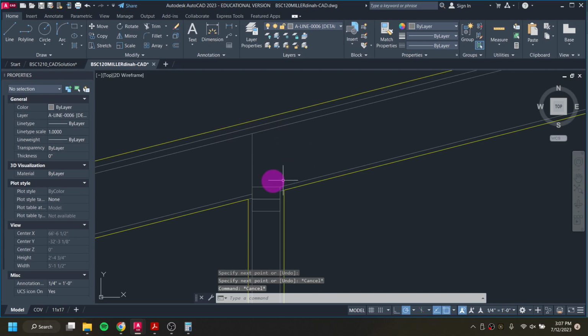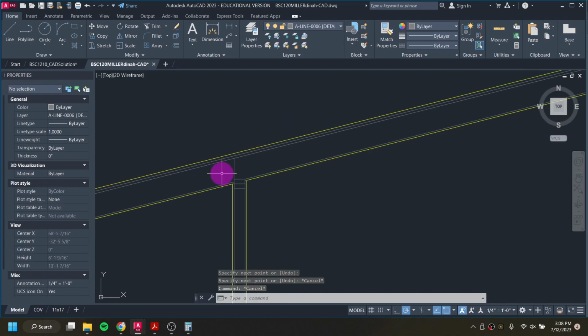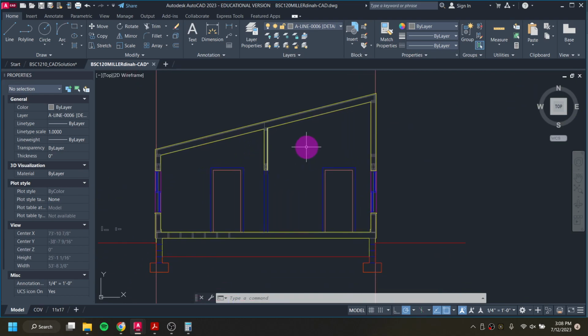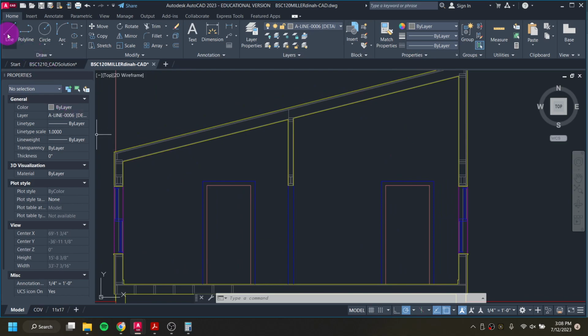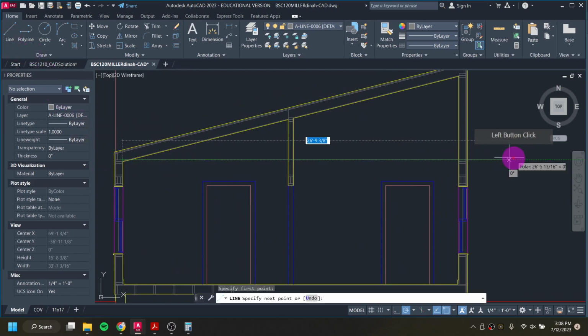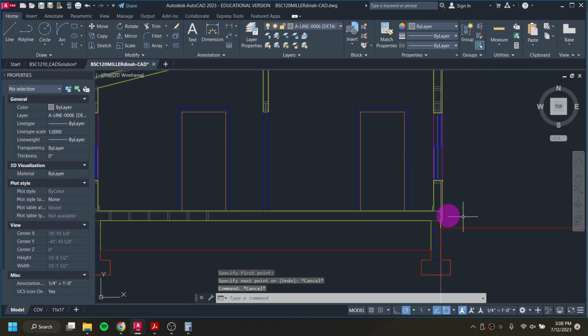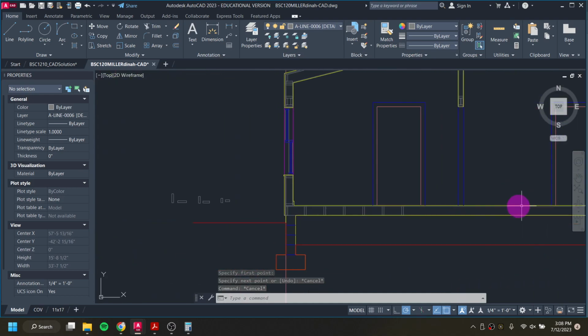What that's referring to is when we're spanning from one 2x8 to another one, so they're lapped at this exact point within the roof. And so, did I not move those straight over? They don't look like they're straight over. No, I did. Okay. I would need another bottom plate over here.